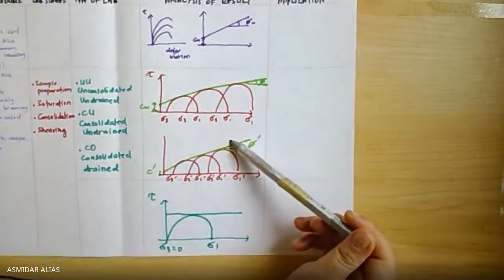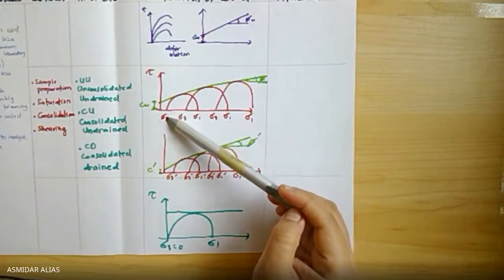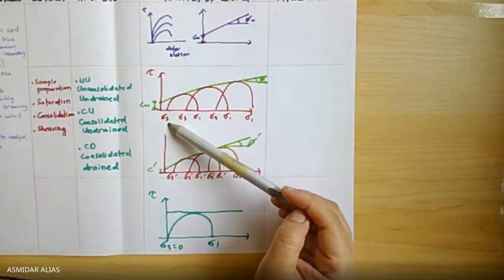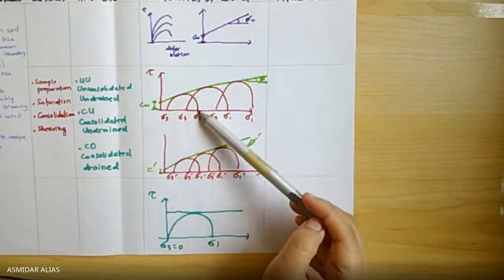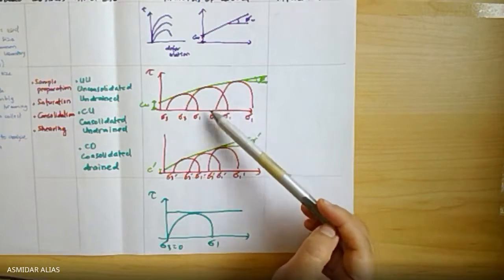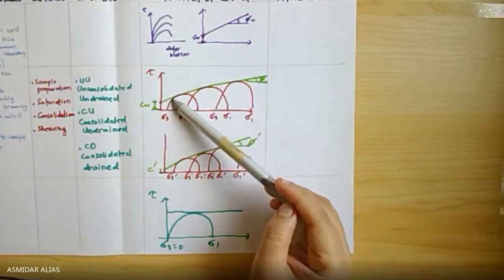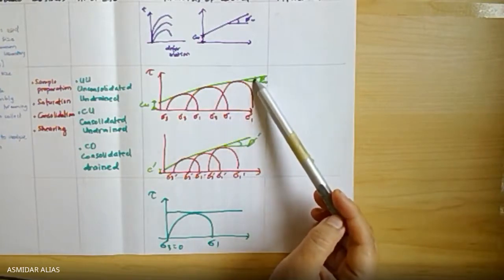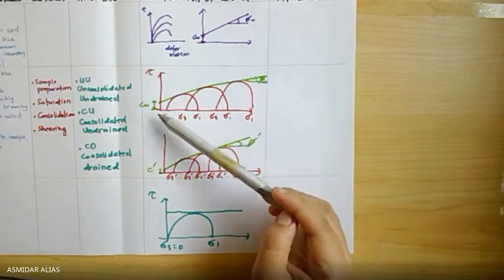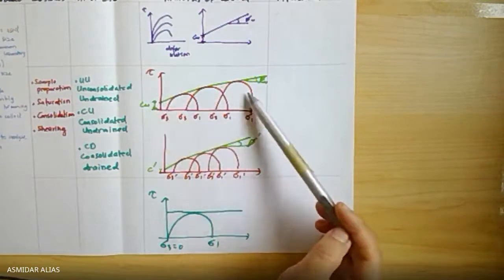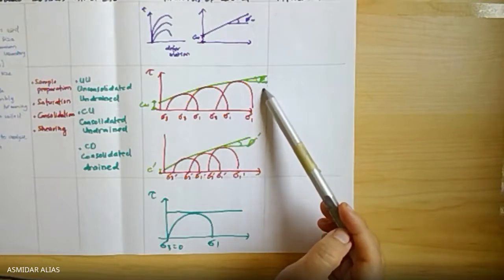Okay, this one is for the triaxial test. Instead of having that line, what you can get from the triaxial test is Mohr circles, given by the cell pressure sigma 3 and the axial pressure sigma 1. So if you get both of the data, you can draw the first small circle. Next you get the second circle, and then the last one will be the last data for your Mohr circle. Then use the concept of a linear relationship and find the tangent of all of these circles. So you get this line. Find the value of phi, and whatever intercepts the y-axis will be your c. If you are plotting sigma 3 and sigma 1, this is for total stress analysis. So in the end, you get phi u and c u.